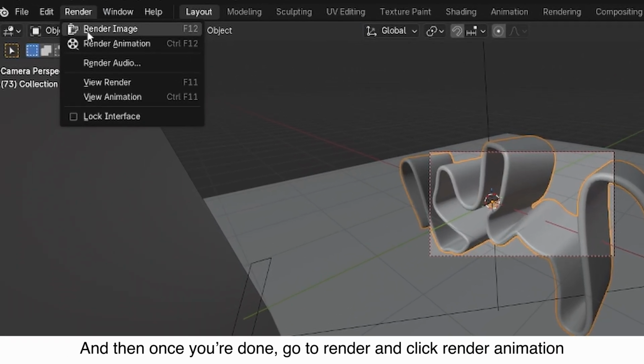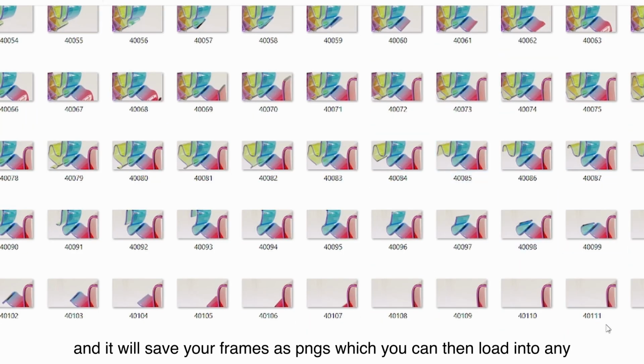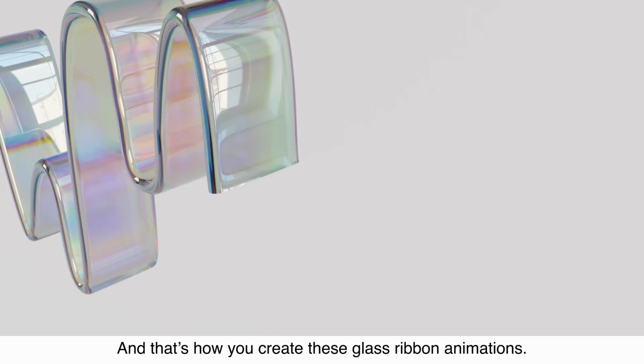And once you're done, go to render, click render animation, and it will save your frames as PNGs, which you can load into any video editing software as an image sequence and export it as a video. And that's how you create these glass ribbon animations.